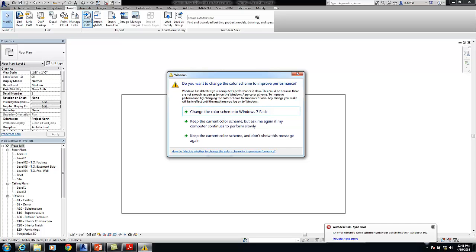Well, maybe I wouldn't put it in a fine level of detail as line work. Maybe I would put it in as invisible line work. That way I can still run clash detections on it, or invisible 3D geometry. But when you have it as invisible, when you bring in the components, you don't see it, like normal. Right, you would have to go in and adjust it and turn it on for visibility.